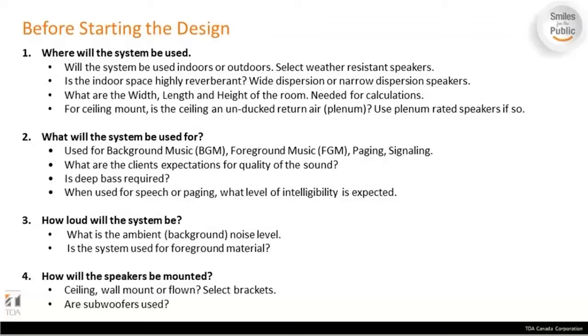Coming to the next point, how loud the system will be. Like I said, it depends on the actual conditions of the room. That would be background noise level. For example, let's say it's a hallway, right? So we know that there's going to be a lot of people in there, so the ambient noise level is going to be high. So you have to make sure the speakers are loud enough so that when an emergency paging or any announcement is made, it's audible.